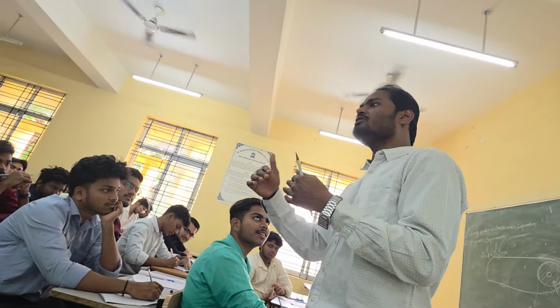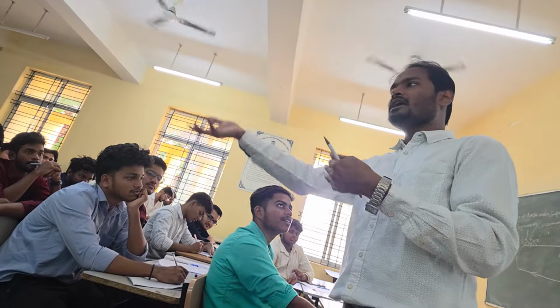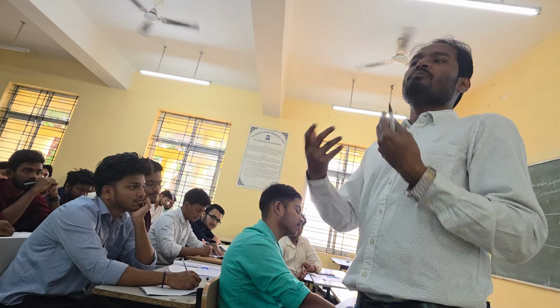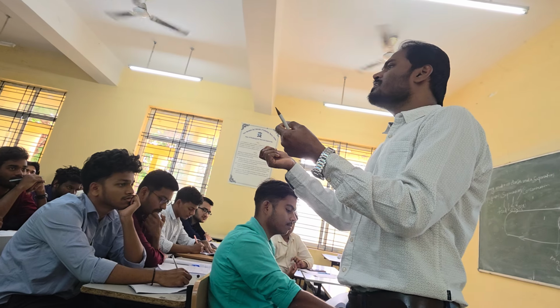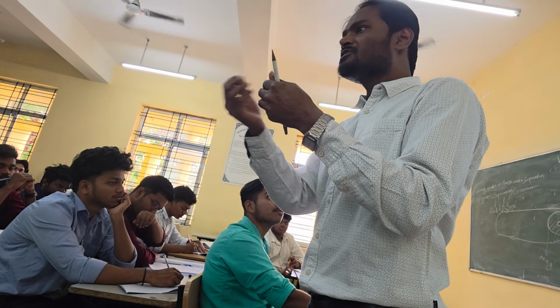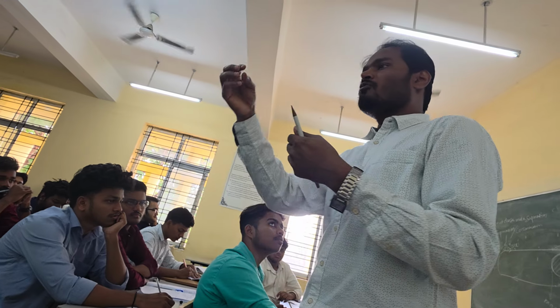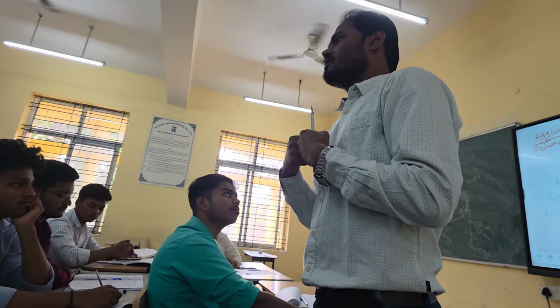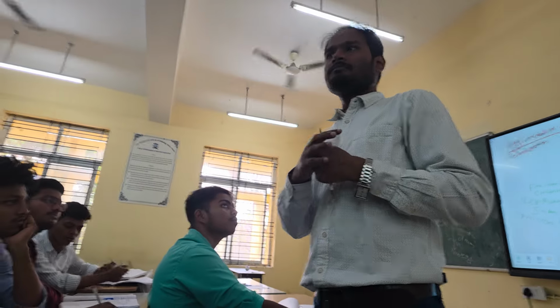In pelletization, you need a critical amount of water. If it is high, it becomes plastic, it may flow. But if it is less, you cannot make it, because insufficient water means binding is not there. Surface tension will be less. Somewhere water is more, somewhere water will be less. So it cannot bind the particles. You understood? This is the real example.